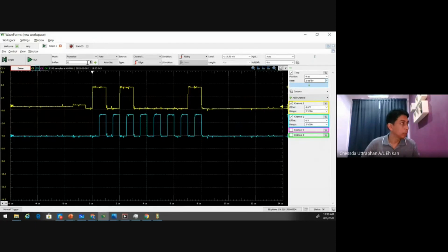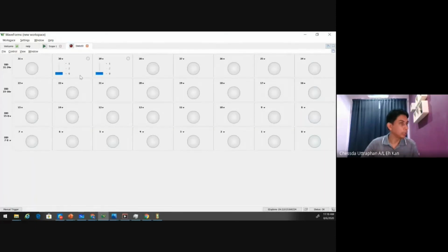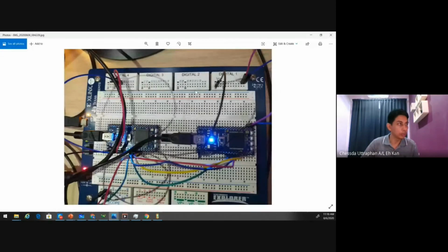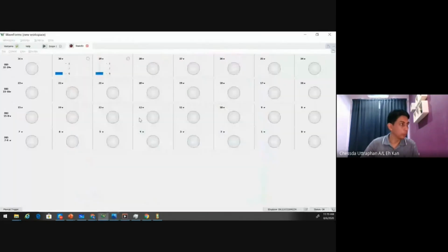So I have the static I/O here. This is the switch, which you can set using this one. You can set whether you want to set this as a switch, and this is connected to bit 30 on the board. So if you look at the board here, this is connected to 30 and 29 here. All right, for the switch 30, and the LED is connected to 0 and 1. So it should be these two. All right, 0 and 1.